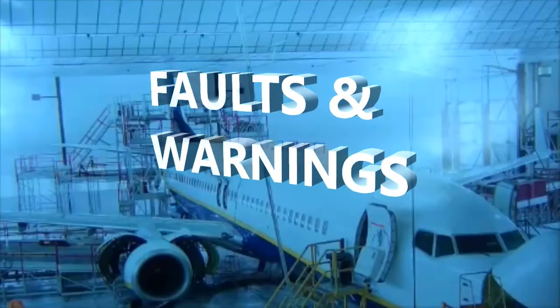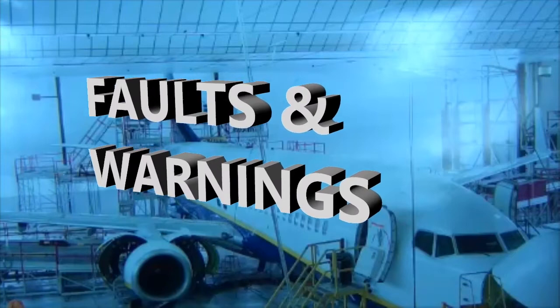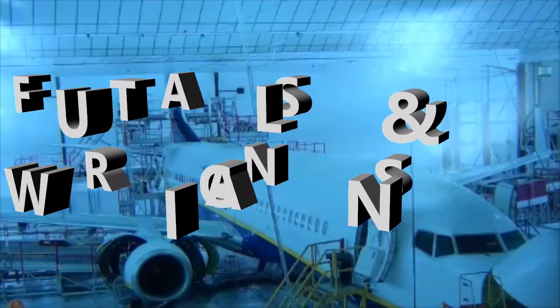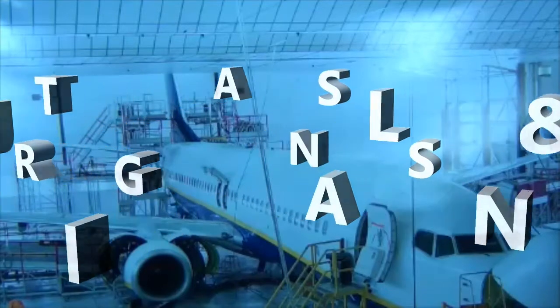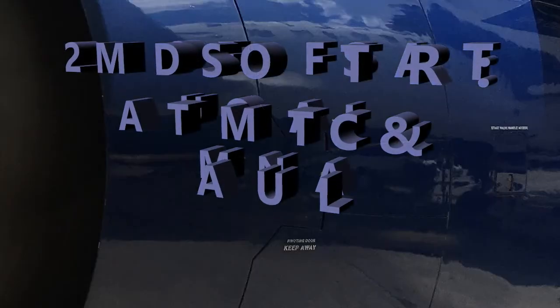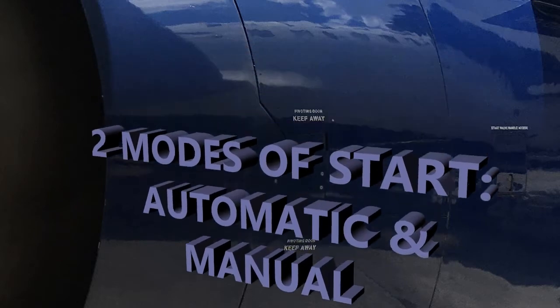What you're going to find across any of the faults that occur is the master caution warning coming on, with a single chime. It's going to be the same warning indication for any of the faults that I'm going to be mentioning later on. Also, keep in mind there are two modes of start: automatic and manual. Automatic is run by FADEC.